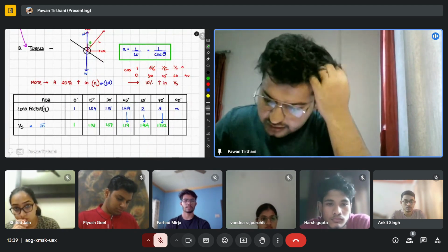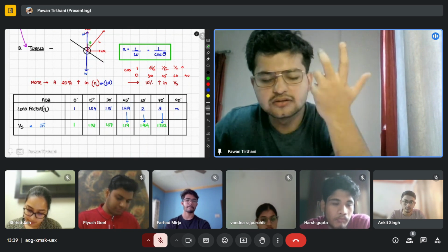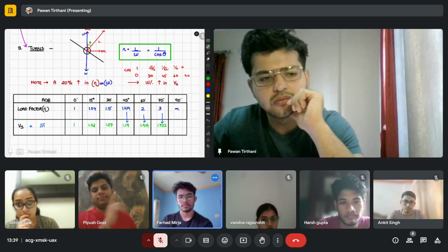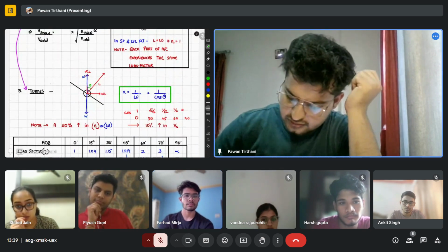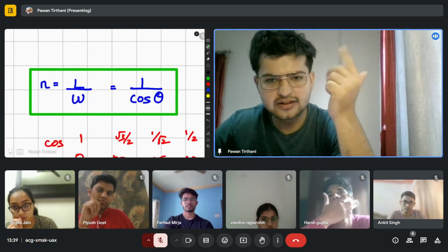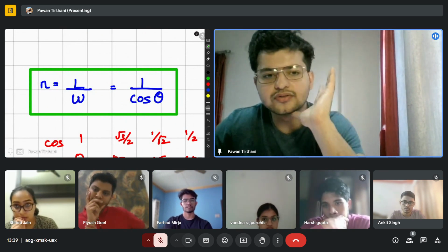Now I hope you guys know your values of cosine. Cos 0 is 1. So 1 by cos. What is the load factor when the angle of bank is 0? 1 by cos 0 is 1. So 1 by 1 is 1. Okay. What is cos 45?